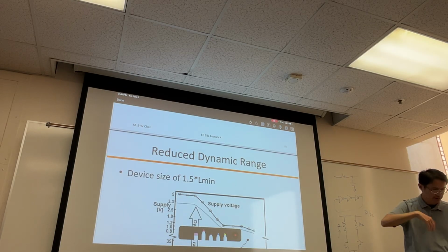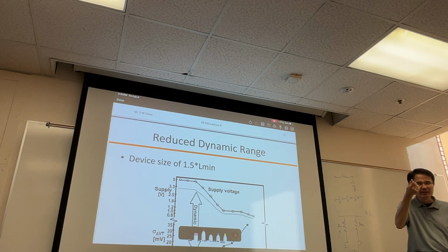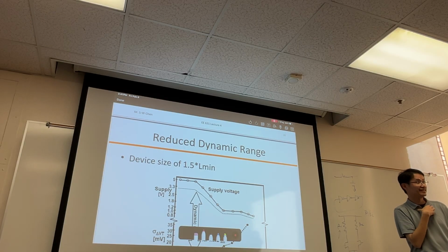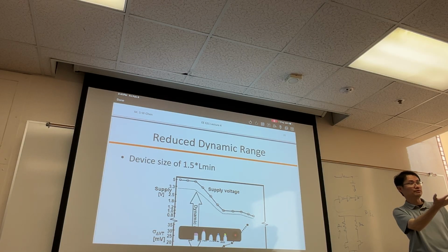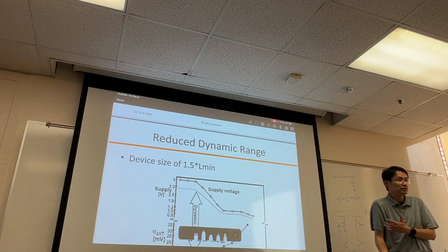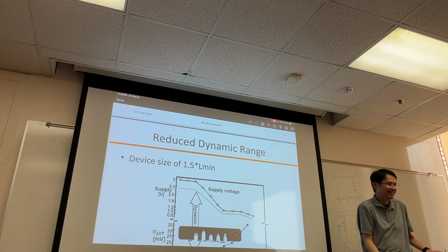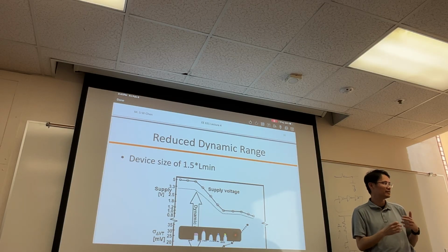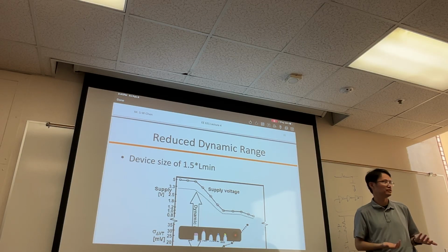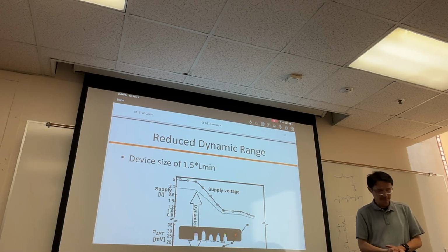So the exact mapping to the physical parameter, doping density, is less important right now, right? So the bottom line, especially for the circuit designer, that's all we care about, right? You never really start designing a circuit and say, okay, tell me what's the doping density. I mean, who cares? All you care about is more like, okay, tell me what's the threshold voltage, right? That kind of thing.